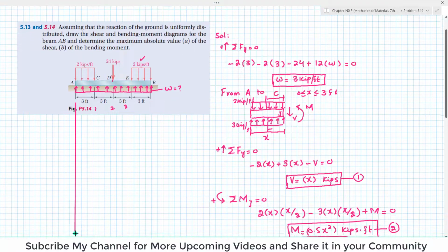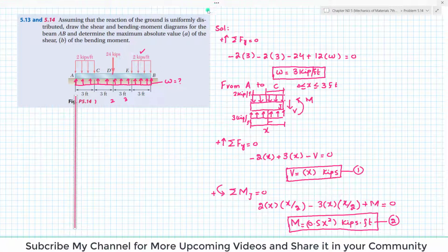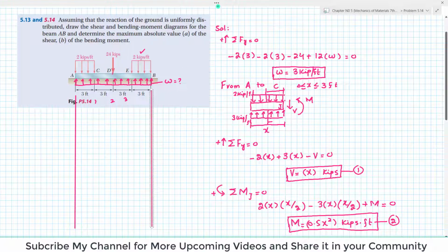So again I have to draw first the shear force, so I will draw it over here. For drawing shear force, I will take a horizontal axis which will show the length. So here we will draw the shear force, that unit will be equal to kips. Let one division be equal to 1.5 kips.